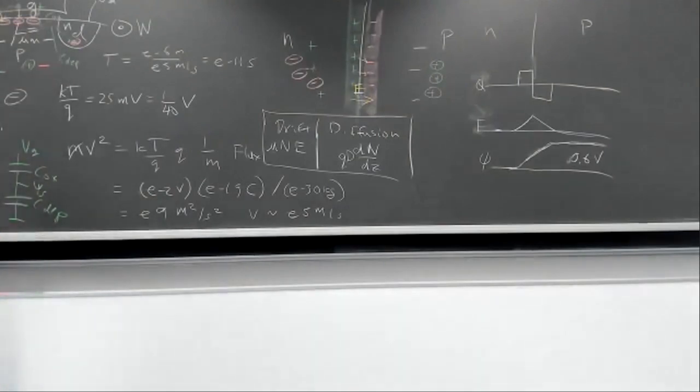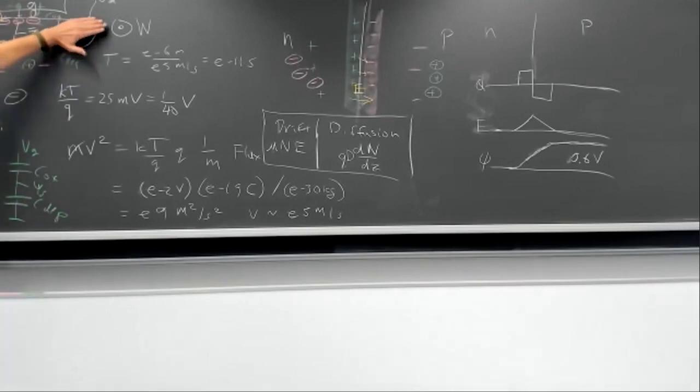But your question was related to this MOS capacitor. Yes, you're right. This is a metal oxide semiconductor capacitor. One plate of the capacitor is the gate. The other plate is this depletion layer or this layer of inversion charge, one or the other. But you do need a source or drain there to get the charge from if you're going to invert the surface. If you just make a MOS capacitor and don't have an N source or drain, or you don't actually need the drain, right?